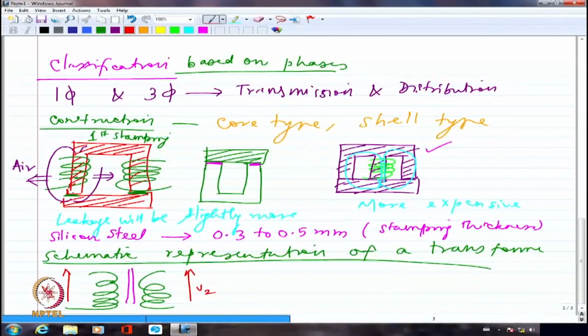Reluctance is some minimum quantity. So that reluctance multiplied by whatever is the flux that I want to establish, that is what is contributing towards the MMF. That MMF is a small quantity in a ferromagnetic core transformer. So I am going to say that to establish a flux in the core, right, minimum current is needed.